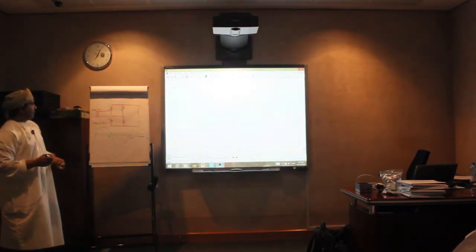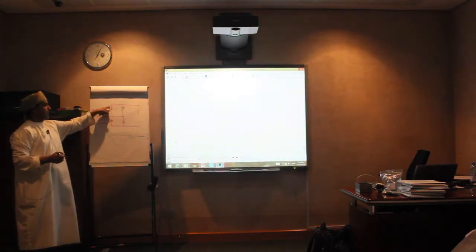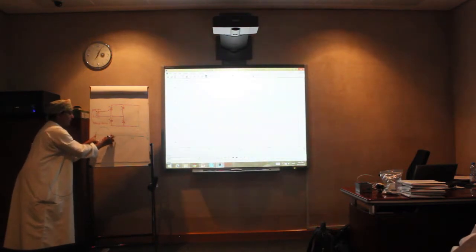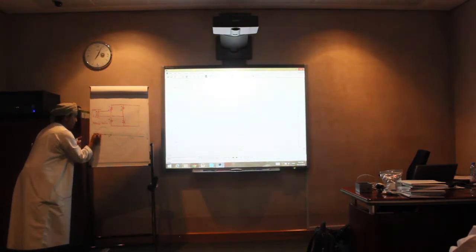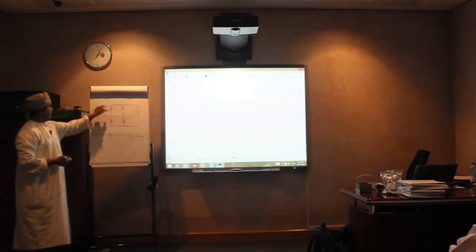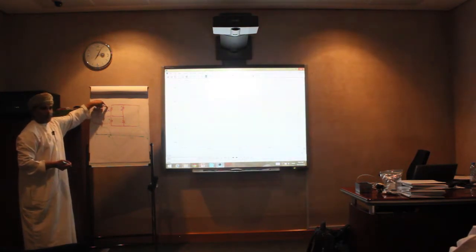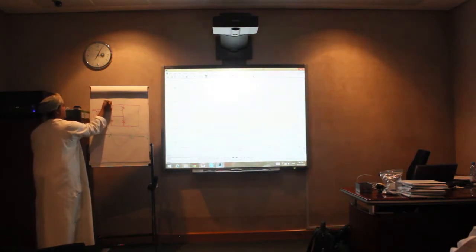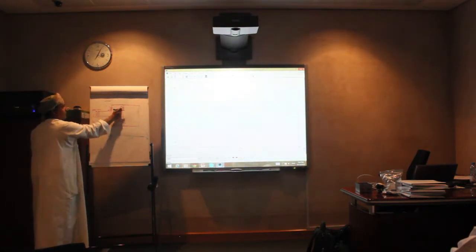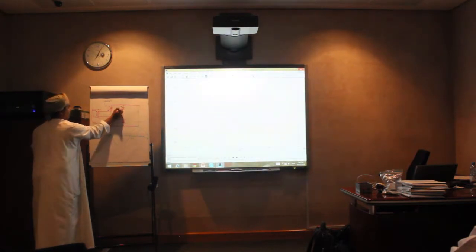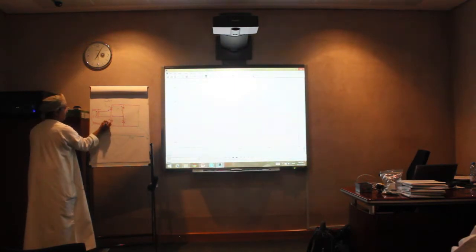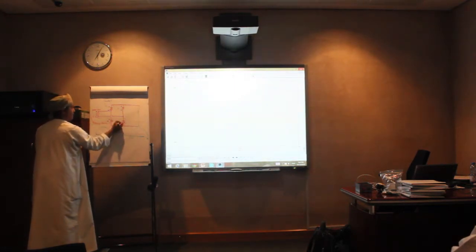So if you look at that one now, the anode here is higher than the cathode on this diode for the first half cycle. I'm talking between this period and this period, from this interval, from 0 to pi, okay? Between this point and this point. Okay. This one, is it in forward bias, right? So this one will conduct. What about this one? No. It's not good. What about this one? No, no, no. What about this one? Yes, it will conduct.